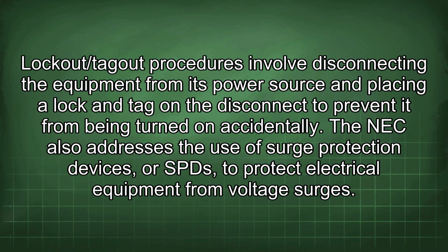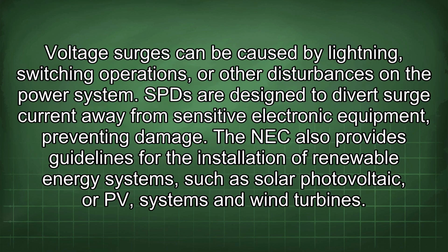The NEC also addresses the use of surge protection devices, or SPDs, to protect electrical equipment from voltage surges. Voltage surges can be caused by lightning, switching operations, or other disturbances on the power system. SPDs are designed to divert surge current away from sensitive electronic equipment, preventing damage.